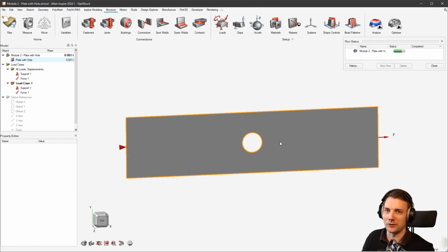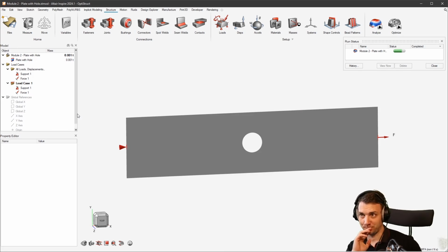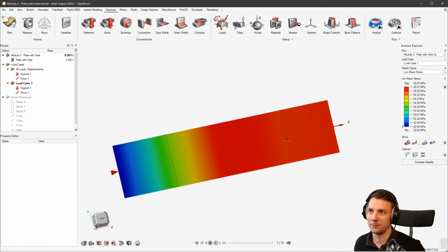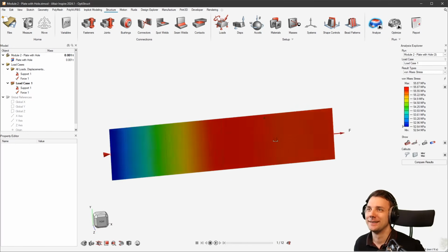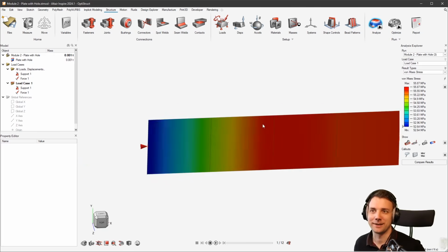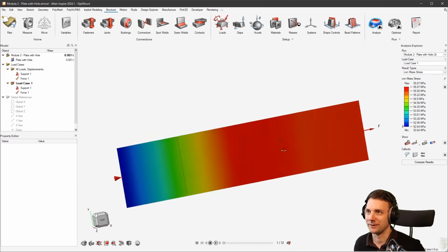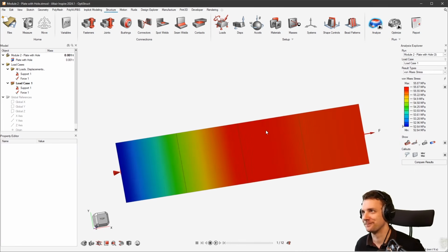If you have small features and define a mesh size with the override, which is larger than the mesh size which is needed to respect all the geometric features you have in your model, then you can end up with something like this. And you can see here now you have 4 elements, but no way that's correct, right? So this is not your geometry, that's not the thing what you want,